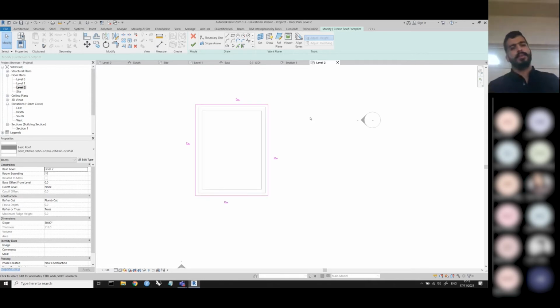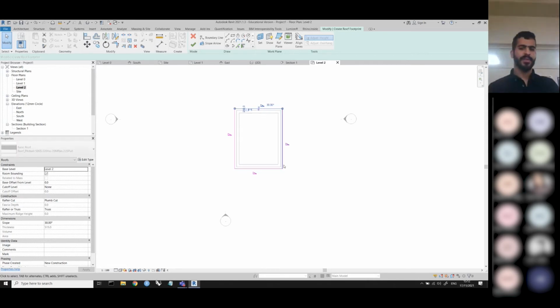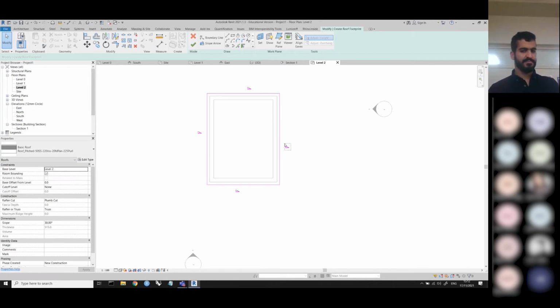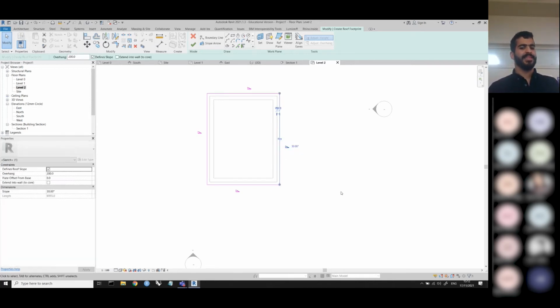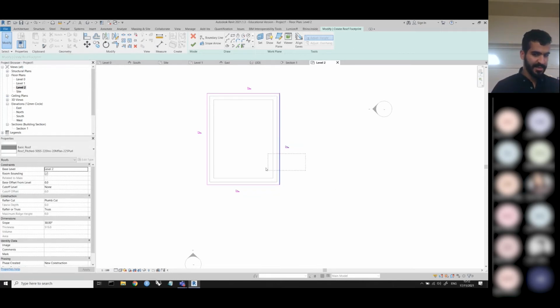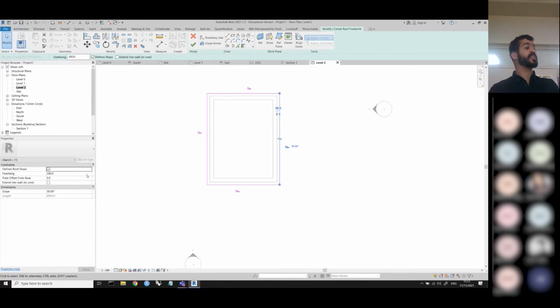Yeah. Okay, so these walls, you see there's a triangle over here, right? This is where you define the slope. So if you click on the line, again, the line has properties on itself. Yeah. So if I untick this, this won't be a slope. A slope won't start from this line. Right? This is how I make hipped or gable roofs, etc.